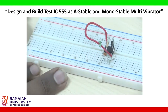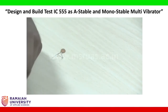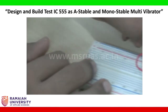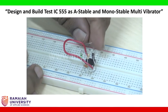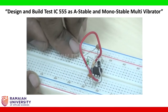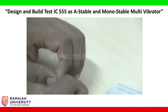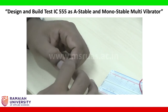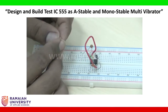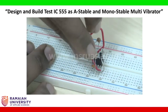Next I am taking a 0.001 microfarad capacitor for the input from terminal number 2. So this is terminal number 2. I am taking this capacitor and placing it somewhere on the circuit board. Somewhere I created one point to connect the input. And a 0.1 microfarad capacitor I am taking, that will be connected from terminal number 6 to ground. This is terminal number 6 to ground. I need to connect. I create the ground somewhere here.